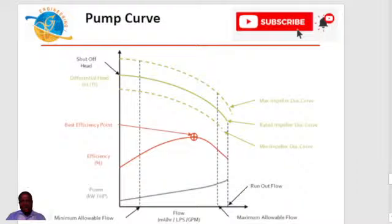At that point of the flow, it is called the run-out point, or run-out flow. So it is not ideal to operate a centrifugal pump at these two extremes. It is not ideal to run a centrifugal pump near this region. The region of what? The region of zero flow or the region of run-out flow.